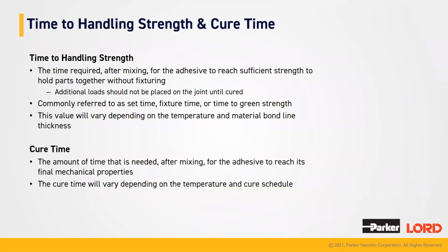Now moving on to time to handling strength and cure time. Time to handling strength is the amount of time that is required after mixing for an adhesive to reach sufficient strength to hold parts together without fixturing. Now, even though you can take the fixtures off and you don't have to have anything holding that bond or that joint or that seam in place, you still don't want to apply any sort of load to it.